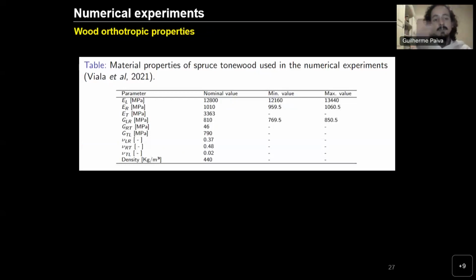So we performed a numerical modal analysis using the finite element method. We consider the orthotropy of the wood. We need 10 properties to describe the mechanical behavior of the soundboard plate.